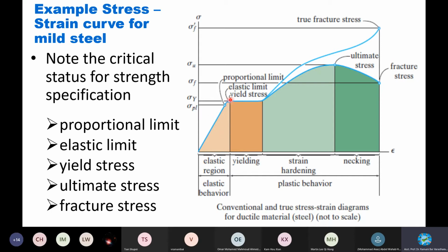this region. After this, even after you stop, see there is no load increasing, the load is removed, load is stopped, there is no more loading applied, but the strain rate started increasing, isn't it? Increasing in strain rate, giving you different crucial points like the yielding point, or the region between the elastic and plastic, and then ultimate stress, and then fracture. Do you understand this? In this case, the yielding point is where it started yielding, changing from elastic to plastic. This is totally a plastic region, right? From this point until this is the plastic region.